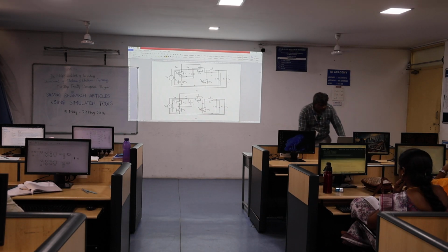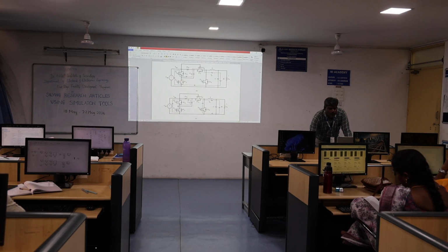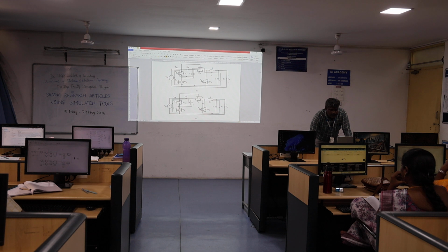Now when we close the switch, this is one of the closed loops. You can apply Kirchhoff's voltage law. Now what is the voltage across the inductor? One end of the inductor has the input voltage plus the capacitor voltage.